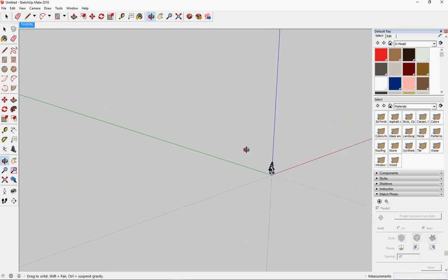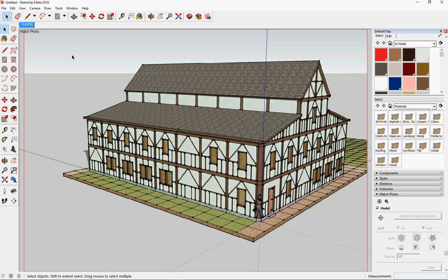You'll see. If you want to recover the photo, we need to click on the left where it says tavern, or whatever name you gave to the photo. So you click tavern, and SketchUp automatically moves and translates the SketchUp world to the plane of the photo.